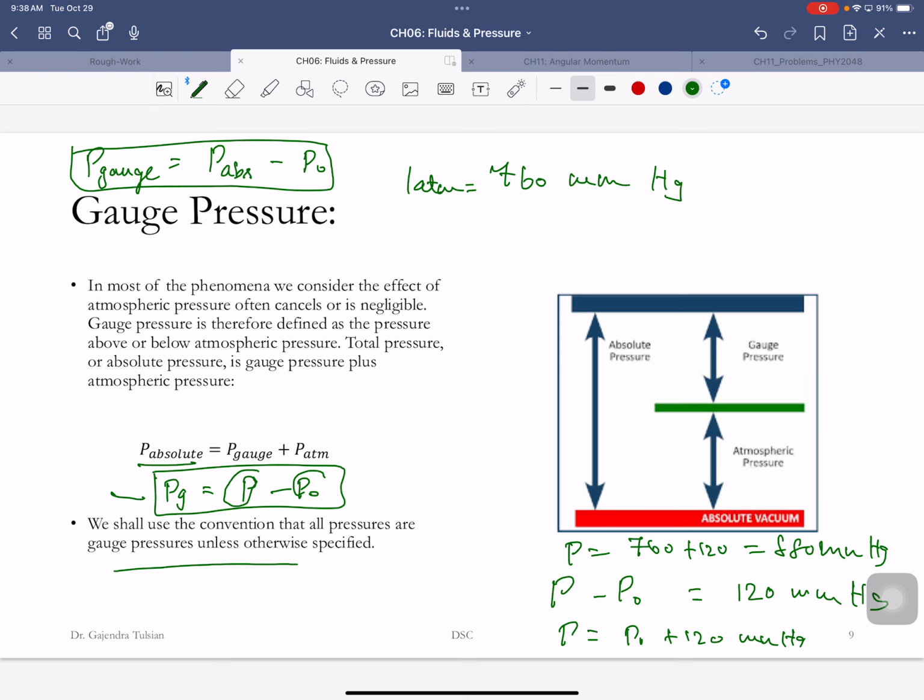So for instance, when you go fill air in your tires at a gas station, the gauge is measuring the actual pressure minus the atmospheric pressure. So in your tires, the gauge measures 30 psi. So the actual pressure is 30 psi plus 15 psi, 45 psi. Okay?